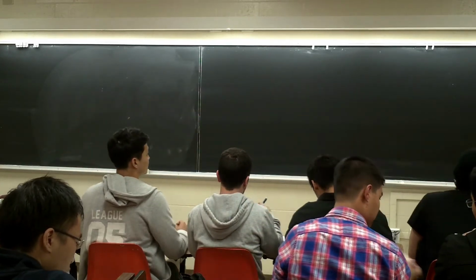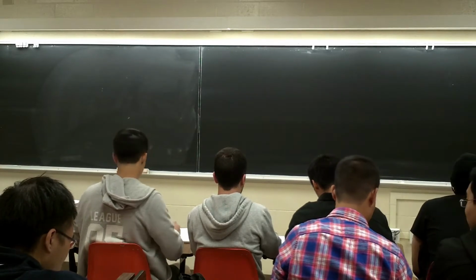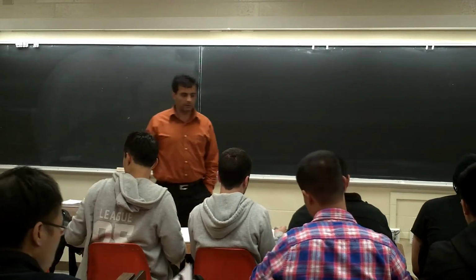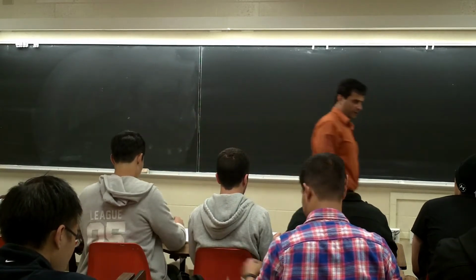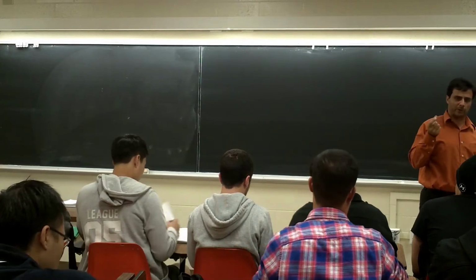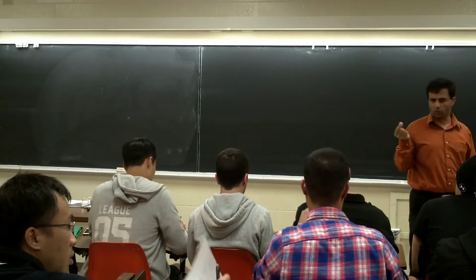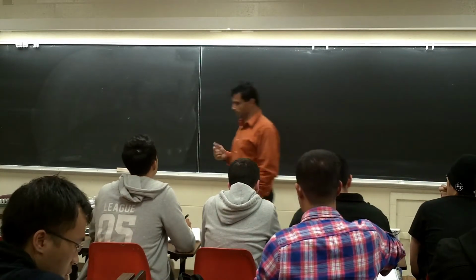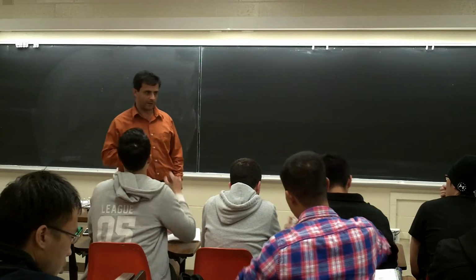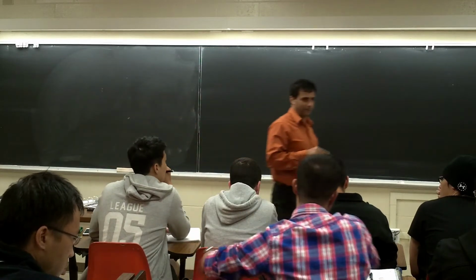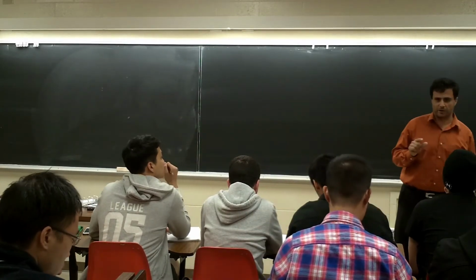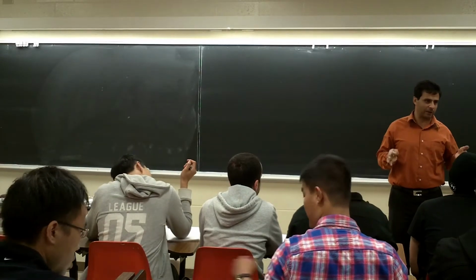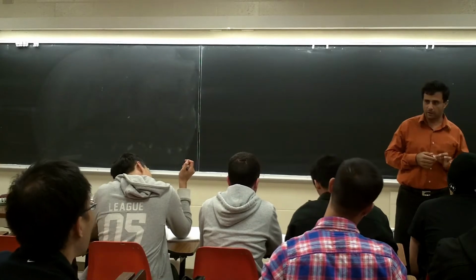So you guys are going to select the perturbation and observation method, because this is the simpler method. You select delta V, 2 volt, 3 volt, something like that for your project. I recommend you use that one because it's easier for implementation. The incremental conductance is more effective and faster, but for the project, you guys are going to do both of them. They're going to give you a good answer. To be kind of everybody does the same thing, you'll use the perturbation and observation.